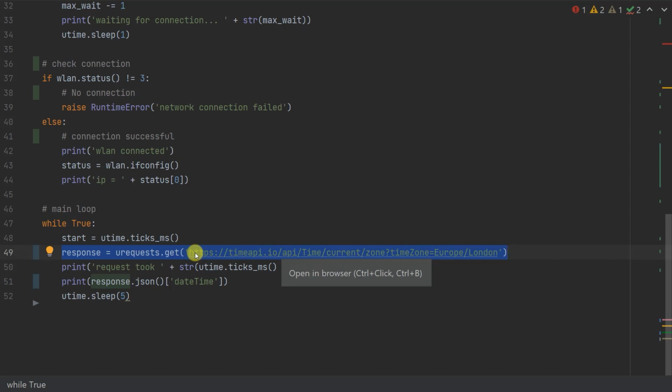And that is something you do need to consider when you're using this web system, that the basic software and the basic interface and controls for accessing the web interface use what's known as blocking code. So certain methods that you're calling take over the Pi Pico and block any of your other code from running until they have finished. Now there are a number of ways around this, which I'll be covering in a second follow-up tutorial to this one. So in this tutorial I'm really going to concentrate on the basics of getting everything up and running.